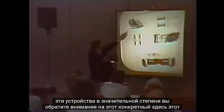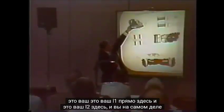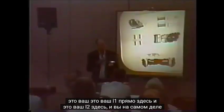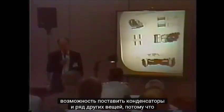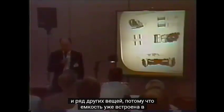You notice on this particular one here, this is your L1 right here, and this is your L2 here, and you're actually tuning this thing by pushing the L1 backwards and forwards in there till it actually matches up with the tuning, and then you've eliminated the possibility of having to put capacitors and a number of other things, because the capacitance is already built into the wire that's part of the coils.